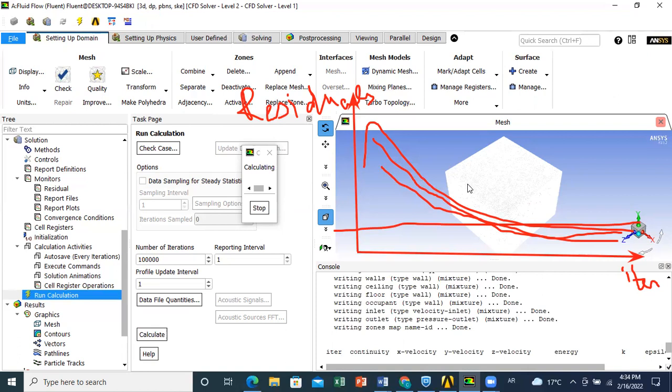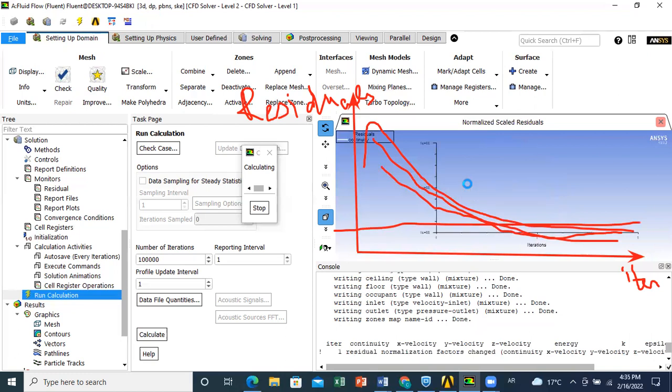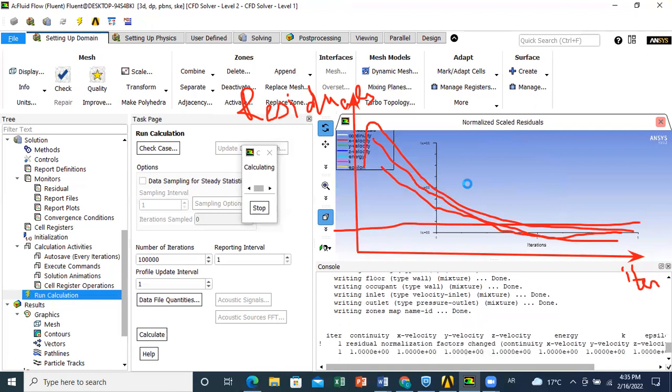So you have several techniques, and you will gain these skills as you go with your project. You need to experiment and do several trials to see what is the best mesh to use. And sometimes we do what is called grid independence for the mesh. What do we mean by this? Sometimes you obtain convergence, your solution is converged, but how do you determine if you are really close to the final solution or not?